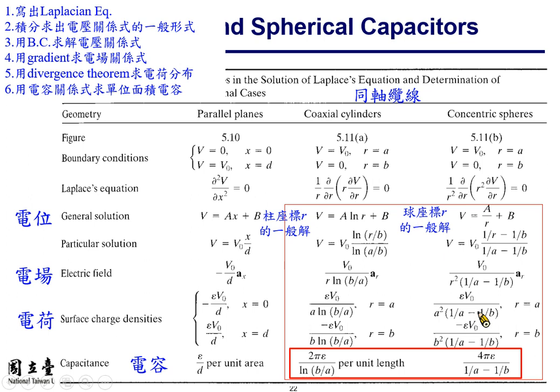But the processing steps are similar. Okay, so you can still derive the expression for unit-area capacitance, or unit-length capacitance. Again, the capacitance is proportional to epsilon, the permittivity of the material in between, and is related to the geometry.